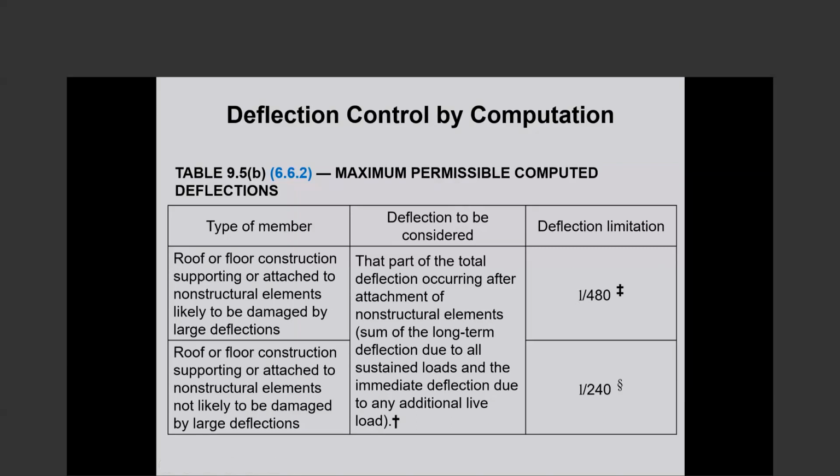What will be the allowable crack width? ACI does not go into allowable crack width. We give you the maximum spacing of extreme tension reinforcement. There used to be things said about the allowable crack width, but then we discontinued that. ACI 318 does not go into that.